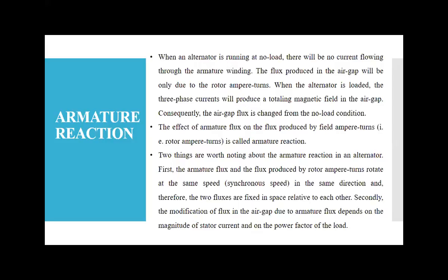Either my load is resistive, or my load is inductive, or my load is capacitive, or it is a combination. Actually, we have a combination of RLC load. Suppose we are talking about this single phase motor. In a fan, there is a motor, and it is a single phase induction motor, but you are aware that inside there is one capacitor. If you remove the capacitor, your fan will not start.